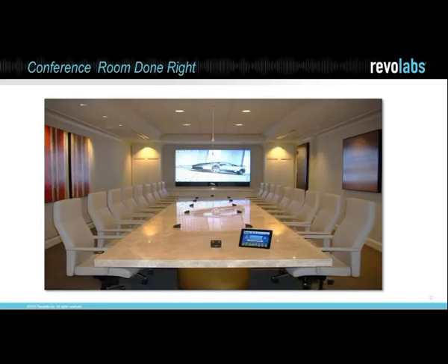You know, we've been talking about a conference room design, and you have a nice picture here. What are the major factors that make this conference room a good design? Well, there's one step I would have taken it further, but what makes this room fabulous is a few things. One, they're using acoustic ceiling panels. Two, they have a nice carpet in this room as well. What would have been nice was to have the artwork be sound absorbing instead of a bit reflective here. But there's enough going on in this room with the soffit drop and the carpet and the acoustic panels in the ceiling. There were also, behind this picture, some acoustic panels on this end to offset the display on the other end.